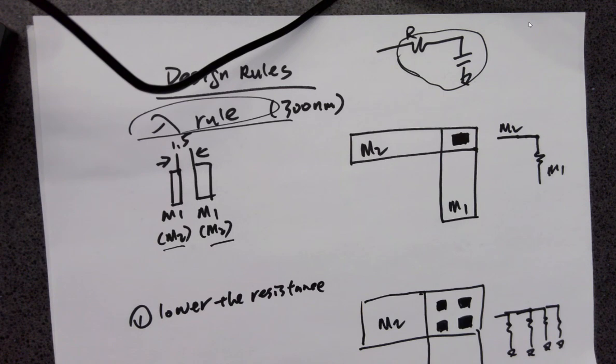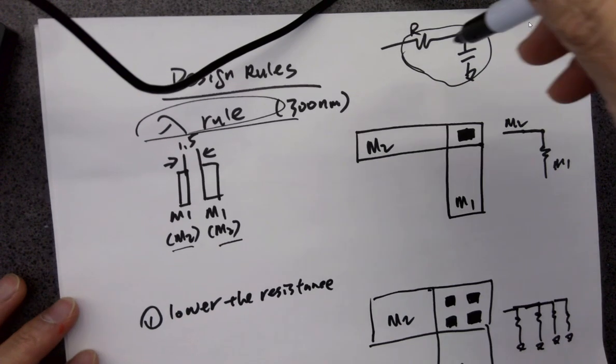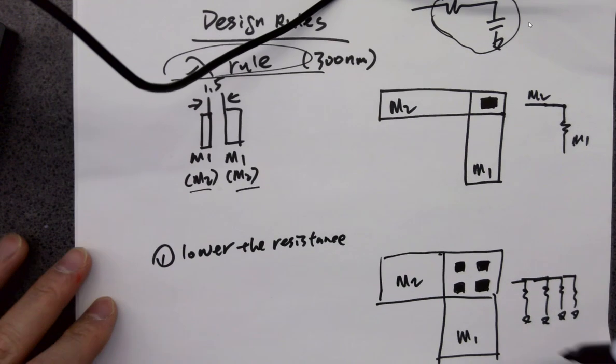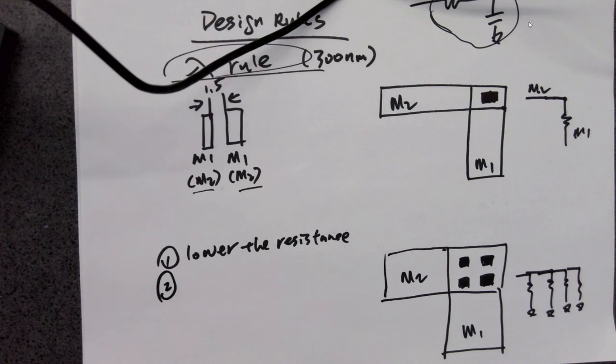It's very significant. So you want to make wider traces of the wiring when you are doing the PCB design, if you have a lot of traces on PCB. It's a very similar concept over here. The trace resistance is really a big deal. So this is the first benefit, to have several backup vias in between metal 1 and metal 2.